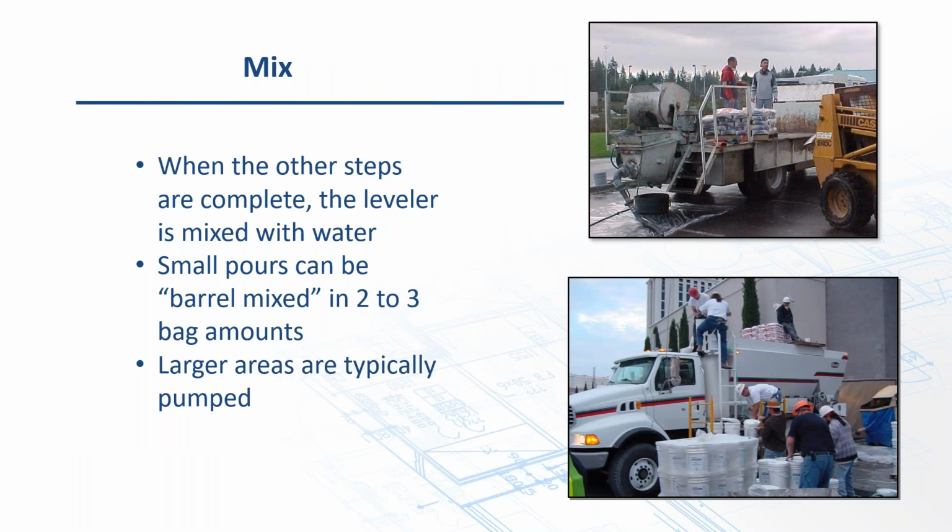There are a variety of different ways to do mixing. You can set up anything from 2-barrel or 3-barrel mixing tubs to pumping. We do a lot of both. Typically, larger areas are pumped. People that really know what they're doing can move a phenomenal amount of material in a day. But at the same time, with an appropriate crew, a couple people at the mixer, a couple people out there pouring, you can pour a lot just by barrel mixing as well.